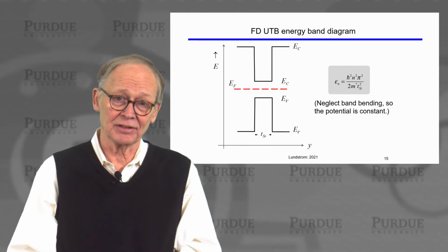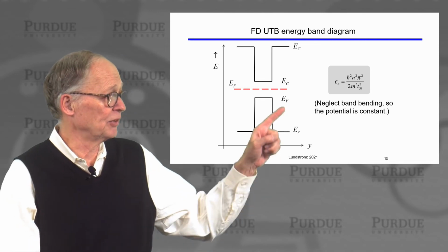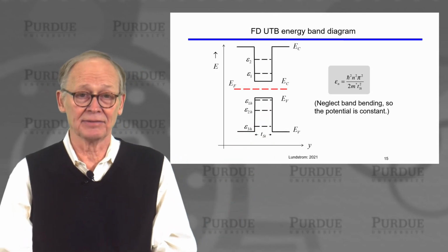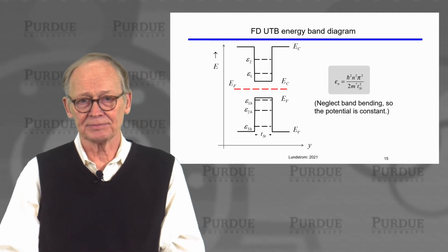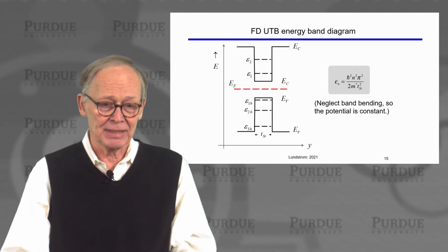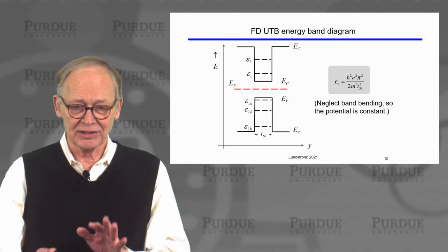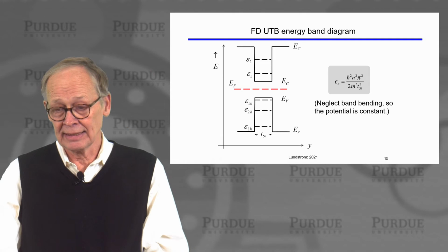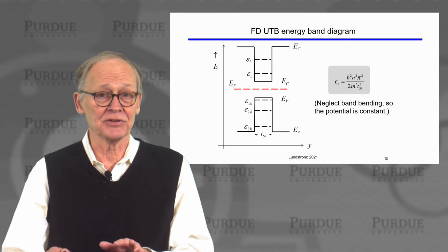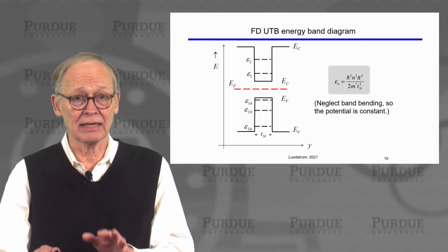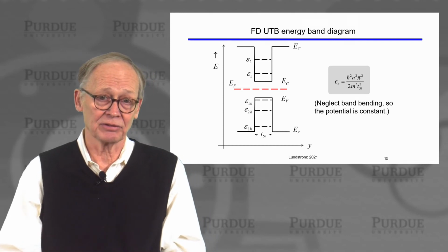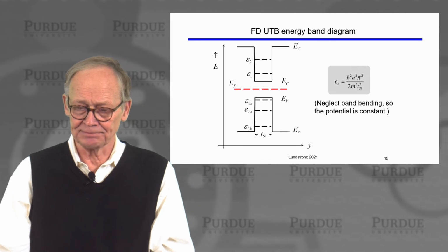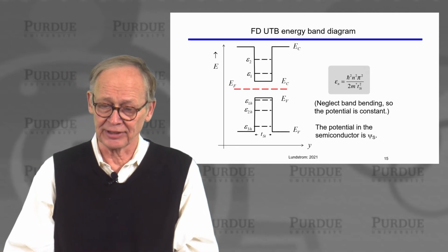We recognize that as a quantum well. There will be some quantized energy states, both in the conduction band and in the valence band, and they'll affect the characteristics. And these effects are becoming sizable enough that semiconductor engineers are careful to account for them when they analyze data or transistor performance. We won't go into that much in this unit, but it's important to know that it's there.